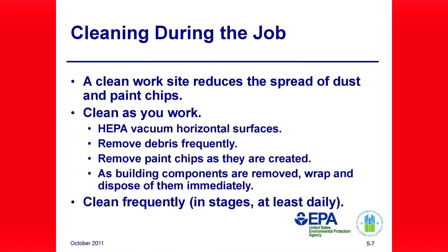As workers come and go during the workday, this debris is easily spread. Periodic cleaning throughout the workday helps minimize the spread of dust. Collect paint chips as they are created. When removing paint, paint chips can spread outside the immediate work area as workers come and go from the work site. To keep paint chips from spreading beyond the work site, make sure that they are collected as they are created. Periodically, HEPA vacuum and dispose of paint chips.